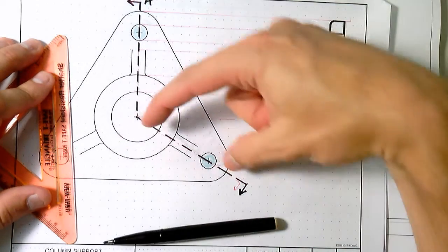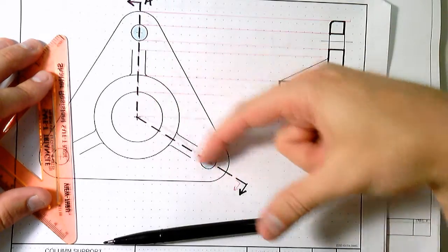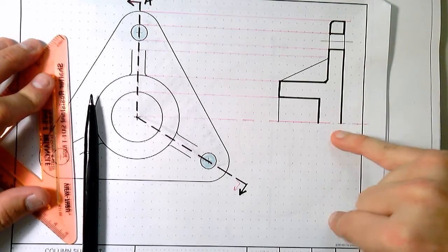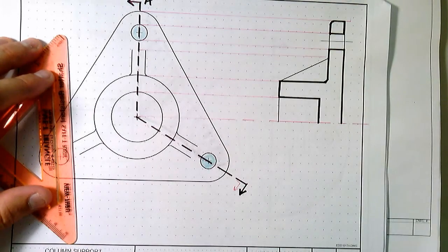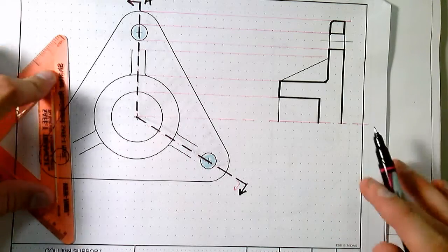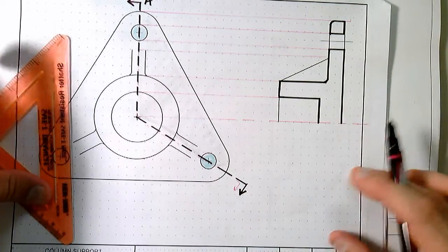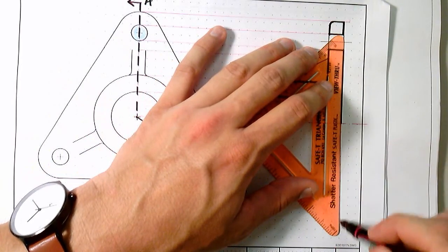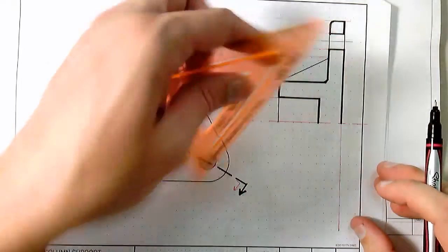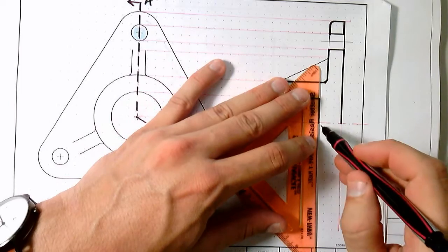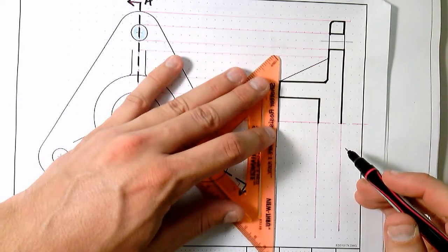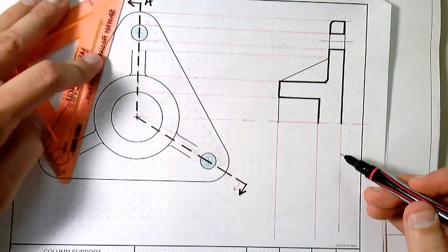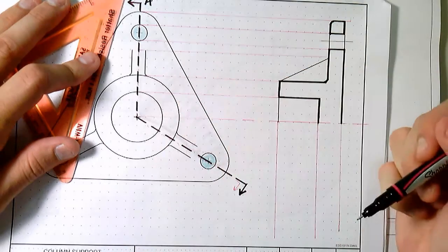Now everything we've done here is the exact same over here, right? All the same stuff is being cut through, it's just at an angle. Well, all we have to do is flip everything we've done here to the side. So that's why if you have these grid spaces, you're going to flip and show the grid spaces on the other side. Before we count those grid spaces, we'll do our projection lines. And the next thing we'll do is count this section so we get our correct diameters.